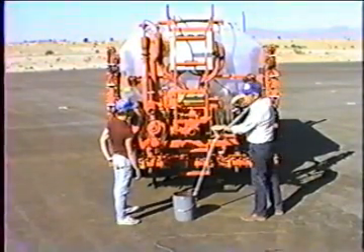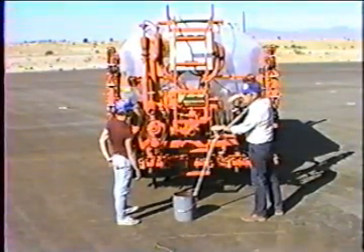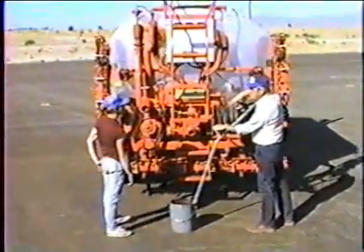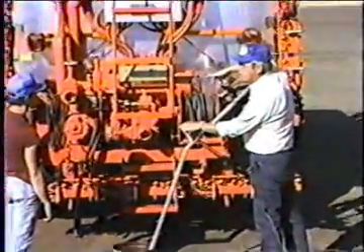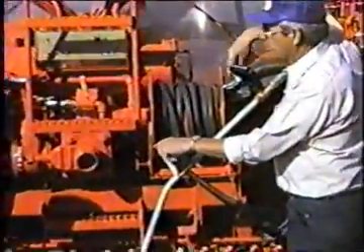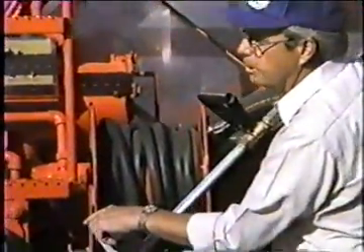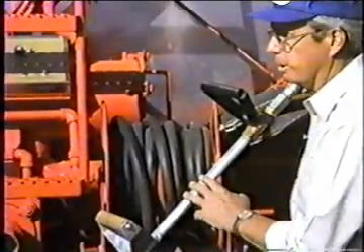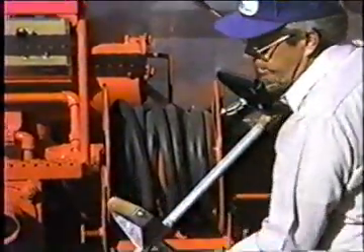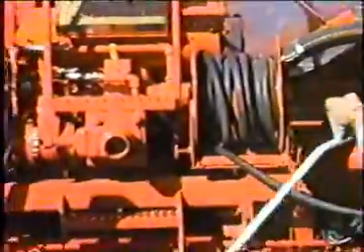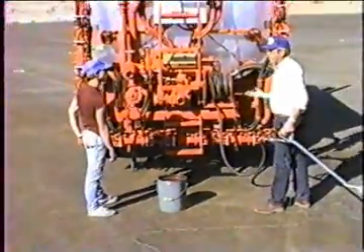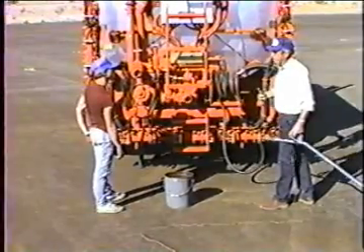That's going to leave the hose full of diesel. The best condition you can leave that hose in is full of diesel. Any residual asphalt in there that runs to the bottom of all the loops will be dissolved by the diesel. So the next day we can circulate anything through it. That's the best way to clean the handgun, because when we get all done, we haven't made any mess at all. We haven't had to pump anything out through the handgun.